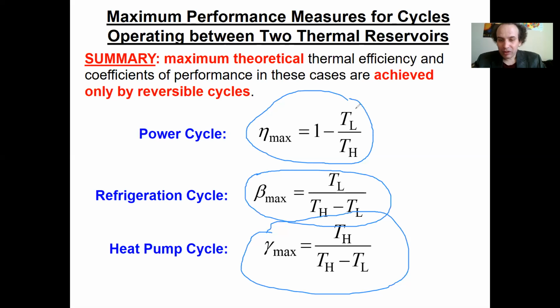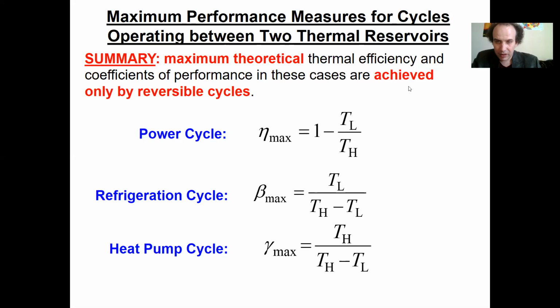So do you understand now how you will check if your heat pump or fridge is feasible or not? Again, find your coefficient of performance. Find the maximal coefficient of performance. Compare and make a conclusion. Is it reversible? Is it irreversible? Or is it impossible? If it's reversible, it's theoretically possible. If it's irreversible, it's really possible, and your efficiency is less than the maximum. Do you understand this? Is it trivial?